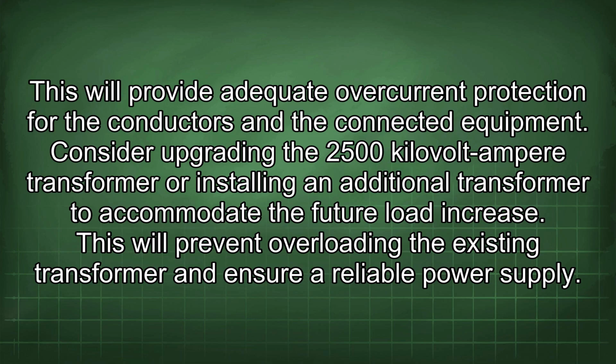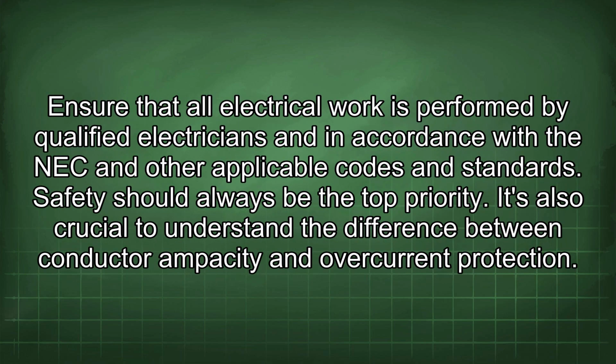Consider upgrading the 2500 kVA transformer or installing an additional transformer to accommodate the future load increase. This will prevent overloading the existing transformer and ensure a reliable power supply. Ensure that all electrical work is performed by qualified electricians and in accordance with the NEC and other applicable codes and standards. Safety should always be the top priority.